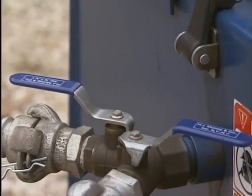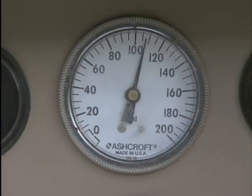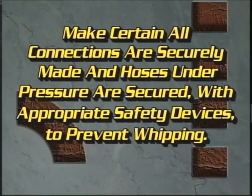Make certain that whatever is to be connected to the compressed air line is not subjected to pressures greater than those given in their manufacturer's instructions. Make certain all connections are securely made and hoses under pressure are secured with appropriate safety devices to prevent whipping.